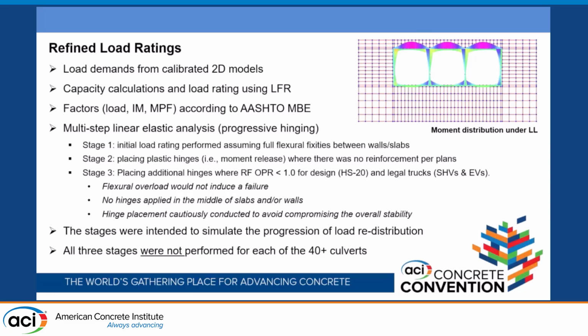Obviously, the model is just giving you the raw data. You need to do the post-processing, apply all the applicable load factors, impact factor, multiple presence factor, which I believe in the standard spec we call load intensity factor, and the 2D calibration factor that we came up with. There was one other step that we did for this project, and that was the introduction of the multi-step linear elastic analysis to capture or model the progressive hinging.